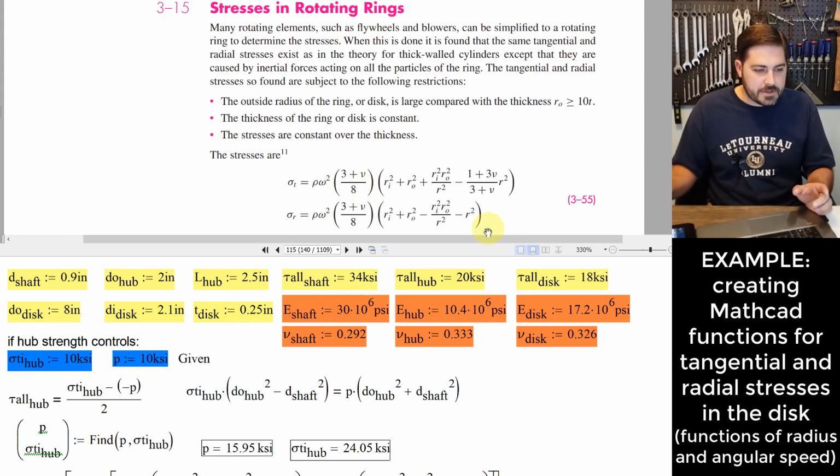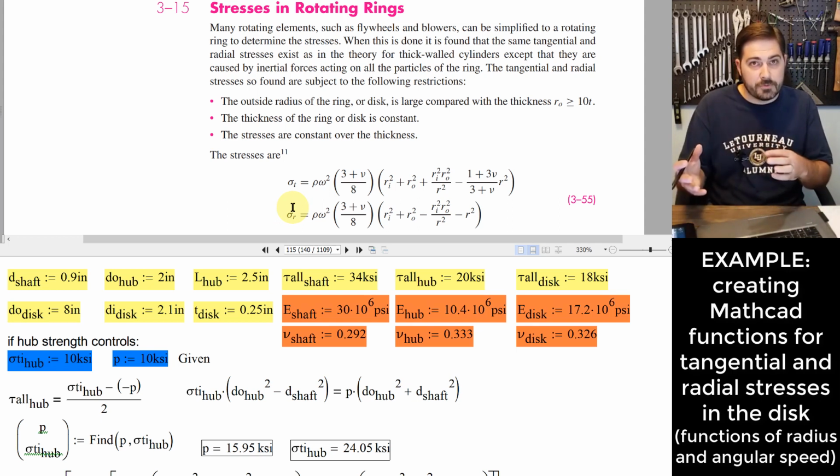What's tricky is there are a couple of things in this equation where we're not quite sure what they need to be yet, right? One of them is pretty obvious. We don't know what this angular speed is going to be of these shafts. We also don't know how the stresses are going to relate to the strength of the material. You might remember that we can go up to a certain amount of shearing stress in the material before it fails.